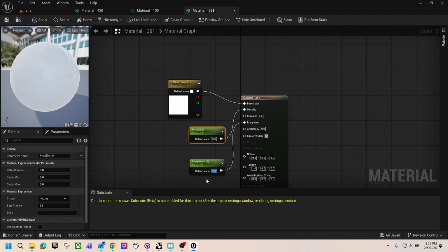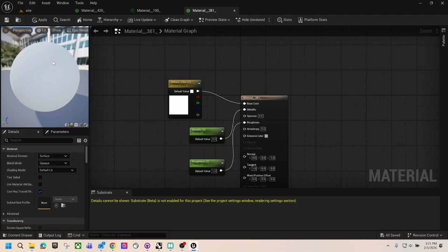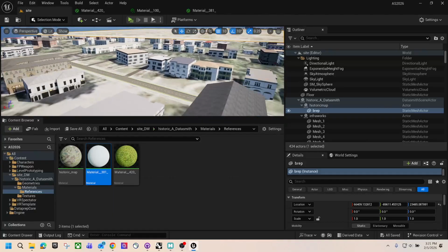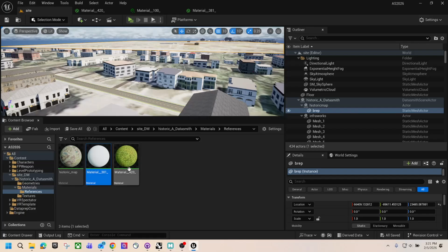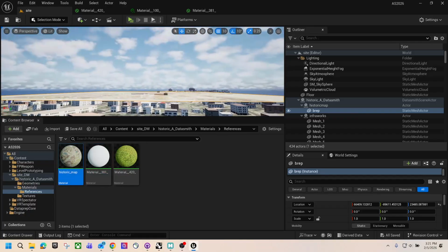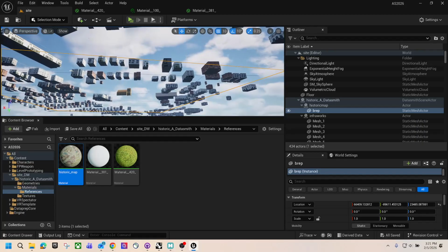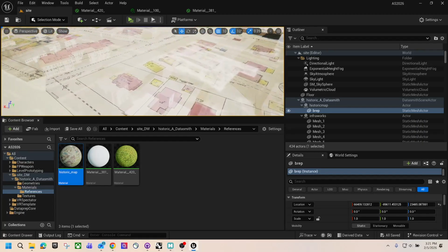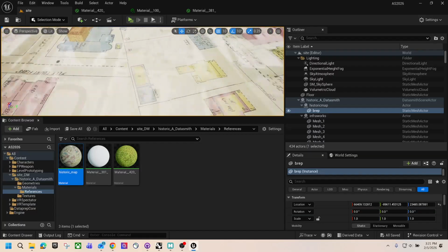I want to make the roughness as 1. Yeah, and then save it. Once I save the parent, everything looks no reflections. Looks awesome, right? So this is a little bit of editing you have to do because when you transfer geometries or shaders from one program to another, sometimes the properties will be kind of messed up. So it all looks nice.